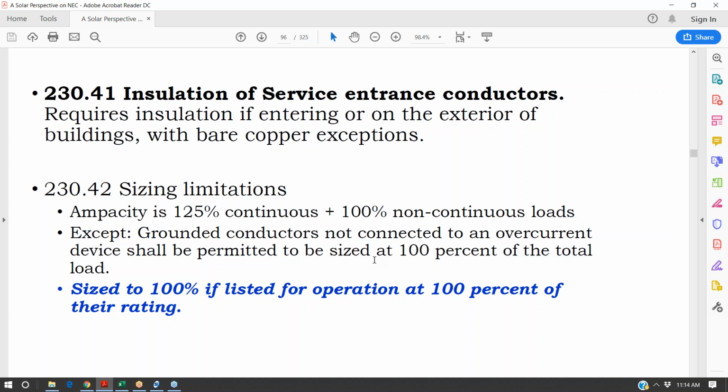At your service entrance, it's connected to ground. It's carrying current back from the circuit. So it is a current carrying conductor, but it's not tied into your breaker. It's tied into a grounding bar or a bonding bar on your service panel. And so remember with our breakers, we don't want our breakers to trip when we hit our maximum load.